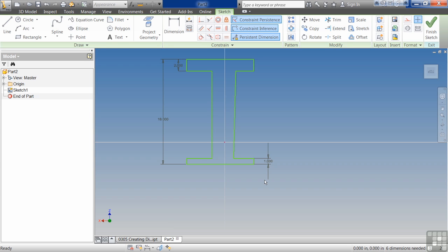Like I said before, we want to add the perpendicular in there and parallel and things like that. But there are going to be times when you need it to be 75 degrees. So therefore, you're going to make sure you don't do a perpendicular, but you want to make the bottom of the angle horizontal. So remember both of those are very useful tools, and you want to use them with each other. They're not mutually exclusive.